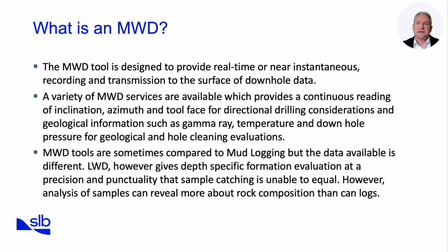It's important to distinguish MWD from mud logging. Mud logging provides surface-based observations through cuttings and gas detection, whereas MWD delivers precise, depth-specific downhole data. While mud loggers may detect more about rock composition through physical samples, MWD offers unmatched immediacy and accuracy in directional control. In the next slide, I will guide you through a video demonstration of the MWD tool. So let's progress.